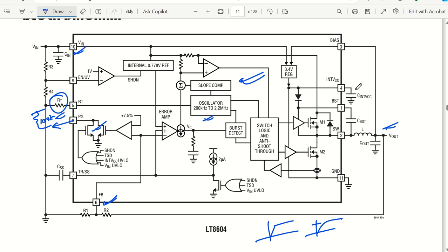Okay. We have an internal voltage regulator, which is used for internal functionalities. That is basically a 3.3 volt regulator inside, so you just have to tie it through a capacitor to the ground. We have a bootstrap capacitor for the internal MOSFET switches, which you have to connect through the SW pin through one capacitor. And this is the inductor that is going to do the switching action to give you the output, and this is the ground pin. We have one exposed pad pin also.